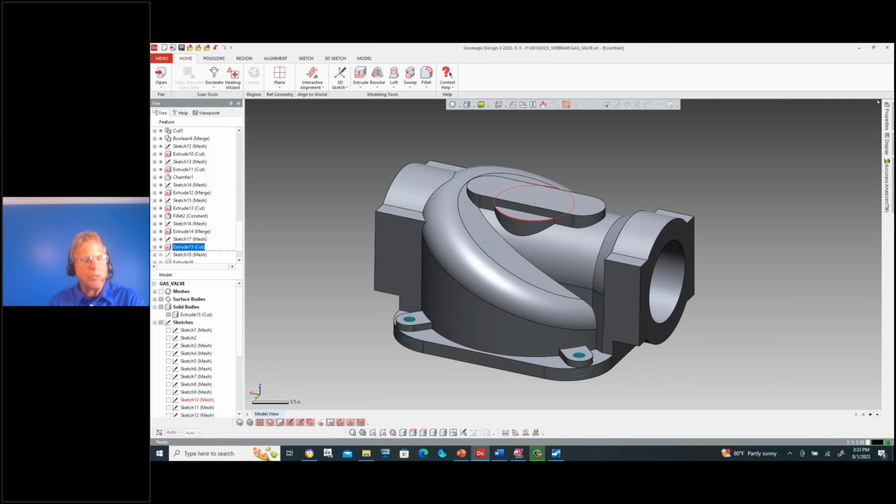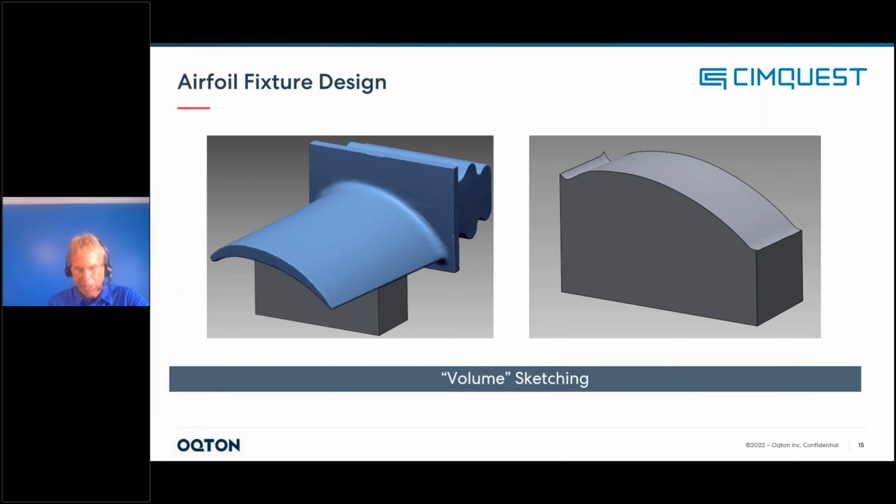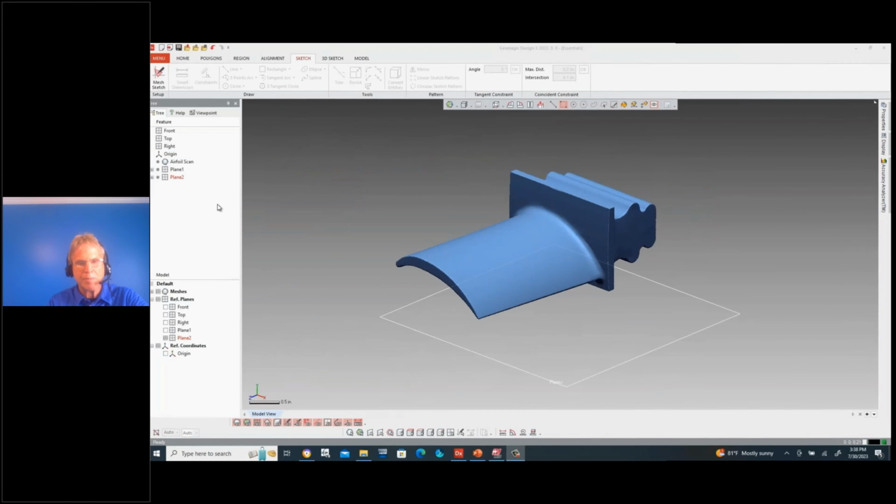And while we do all this, we can make sure the holes, the tabs, and the base plate all are concentric to each other. So again, we can model in our design intent, our manufacturing intent directly into the product. Finally, we end up with little tabs on the sides of the part. We pass this into Mastercam. And then in the Mastercam user interface,